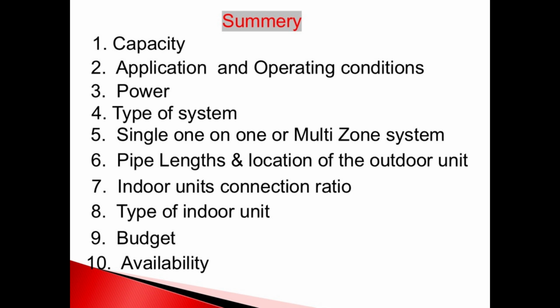We've covered many factors to consider when selecting a split unit. In summary, know the heat gain and heat loss for your application. Determine whether you need a standard heat pump or a low ambient cooling unit or low ambient heating unit. Check the power availability at your site and the power requirements for the unit. Decide on the type of system.